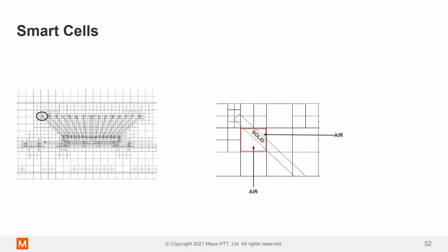This is an example of a smart cell. We have a solid region which is sandwiched between 2 fluids on either side. This is basically a 3 control volume grid cell. There are planar surfaces separating the fluid, solid, and the fluid region, as we can see over here. This technology, in conjunction with our boundary layer treatment algorithm, allows users to have a relatively coarse mesh whilst maintaining accuracy in the overall model. We can have multiple control volumes, up to 12 within, for example, this particular cell.